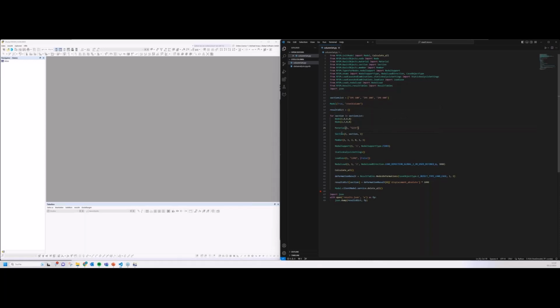Then we're going to define a section. In that case, as it is very simple, we only have one section, so we give it the number 1. For the name of that section, we define it per this list and the actual counter in the for loop. So having the nodes, the material and the section, now we can define a member, as you can see here, with all the attributes. And finally, in order to make it a feasible structural system, we need to give a nodal support. Here we just clamp it at the first node.